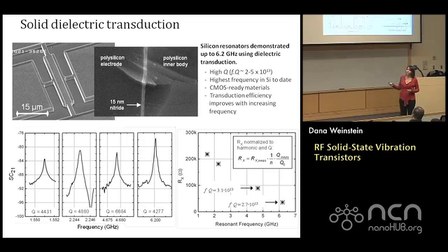And in order to deal with it, in order to be able to measure the mechanical behavior, we had to use the fact that the capacitor acts as a mixer, in terms of the driving force being proportional to the square of the voltage. We actually applied an LO signal across one side and an RF signal on the other, so we could measure at the other port at another frequency. So we get only the mechanical signal, not the feed-through.